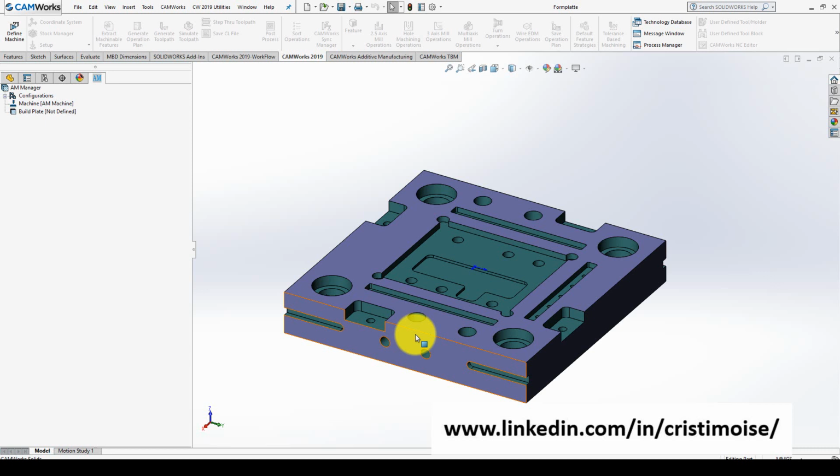In the older version of CAMWorks, you can use curve features, let's say, for a complex curve, but when you define a curve feature you would not have the ability to use it in contour milling for chamfer machining. The CNC compensation options are disabled, and you have some restrictions in lead in, lead out. For the new version, you will have all these options available.